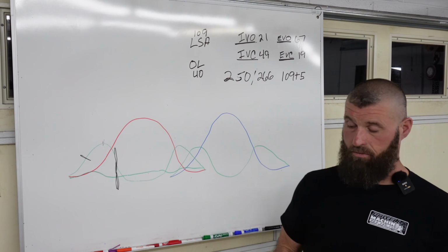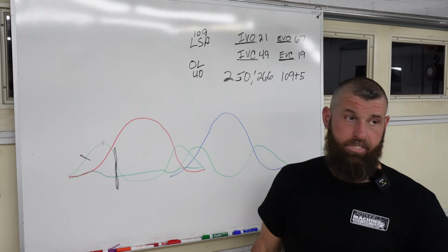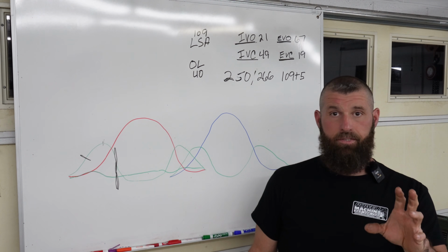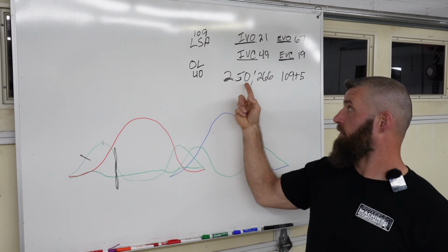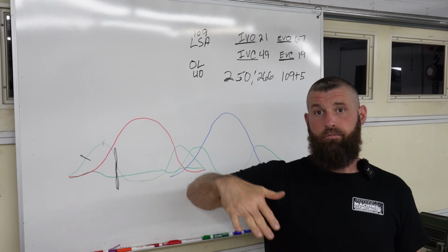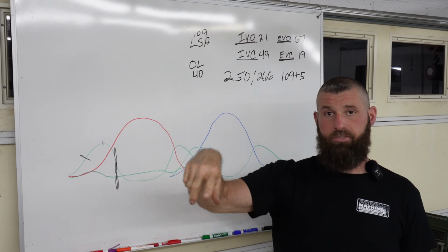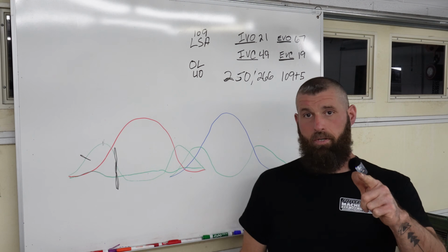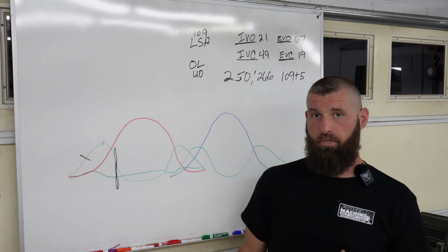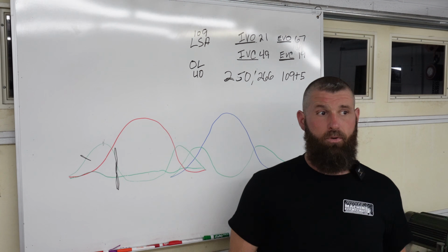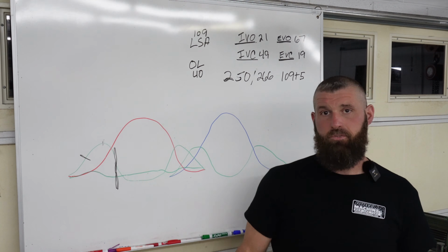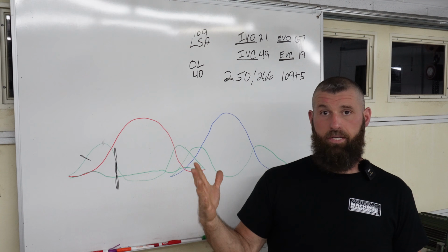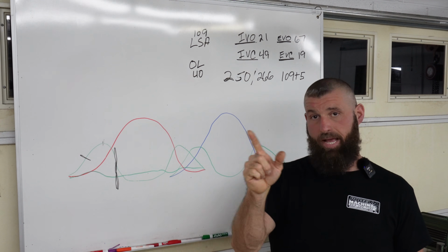Another thing quickly, because this has just got way too long, I apologize. Another problem that I see nobody talk about is how much bigger do you make this number and this number for spring pressure, deflection, and RPM. The bigger the RPM gets, the more spring pressure, and the less rigid the push rod is, this number's got to grow. So luckily, I'm friends with a lot of smart people, and a good buddy of mine, Ben Schrader at EFI University,